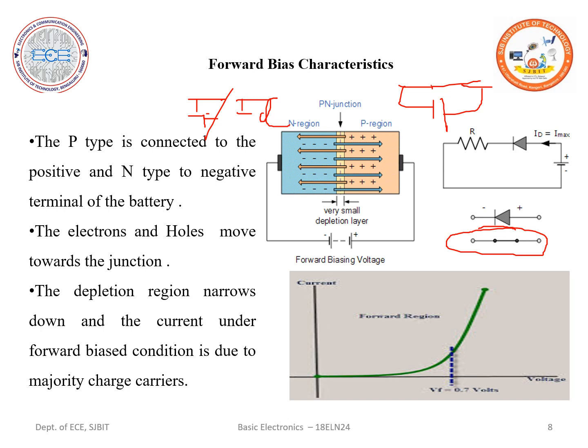Now when I plot a characteristic curve of current versus voltage, there is a voltage which we call the threshold voltage. Till the diode reaches the threshold voltage, there will be no flow of forward current, which we call IF, and the voltage we call VT, which is nothing but our threshold voltage.